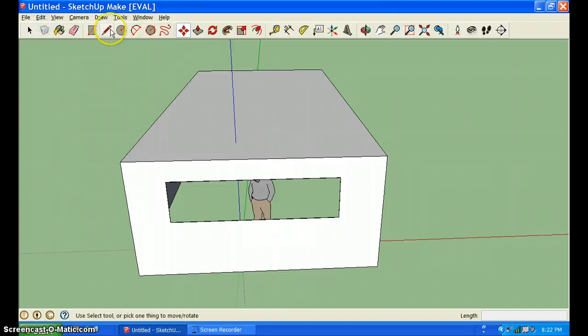And now I'm going to start that draw line again. I'll show you the correct way to do it. I want the midpoint. On edge, midpoint. That's what I want. Draw the line. And I'm looking for midpoint on this side. Yeah, there it is, midpoint. That's what I want. Now the move tool will actually work for me.